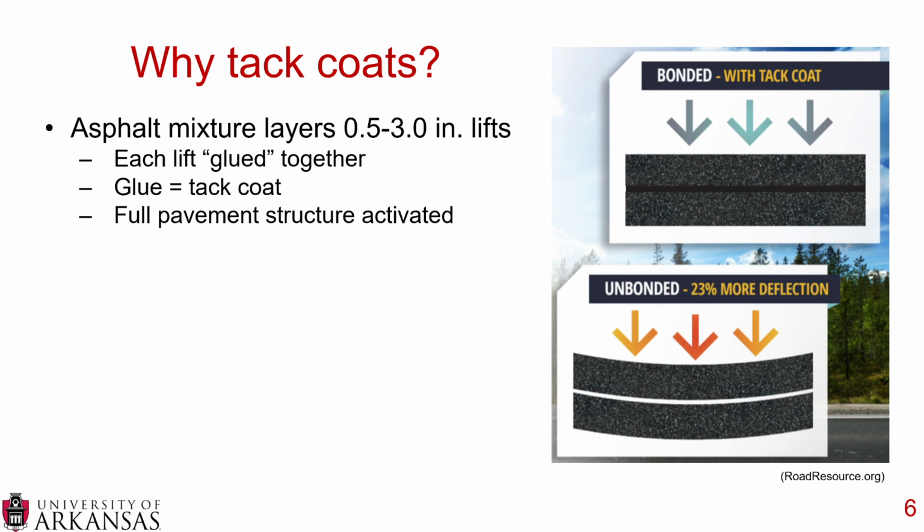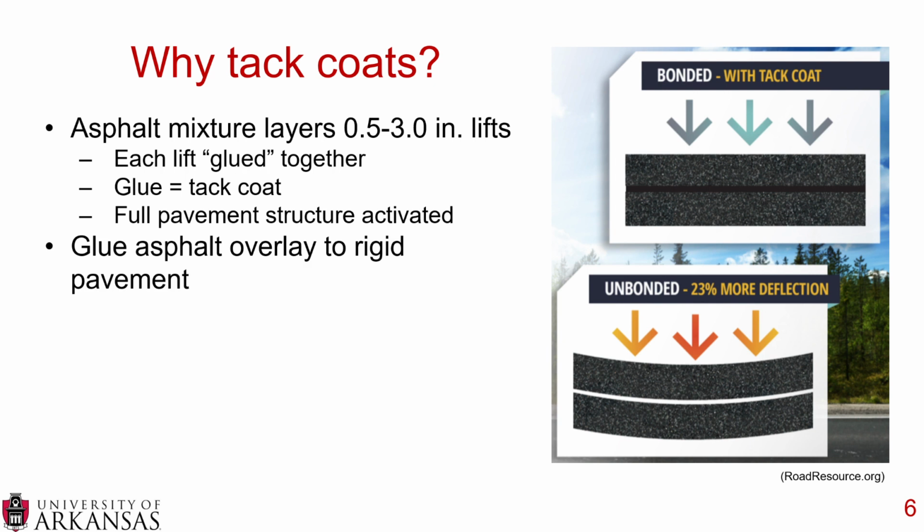Whereas if you do not have that tack coat, essentially you have a bunch of plates stacked up on each other and they all act independently, and you get a lot more deflection and you don't get the strength that you designed for in your pavement structure.